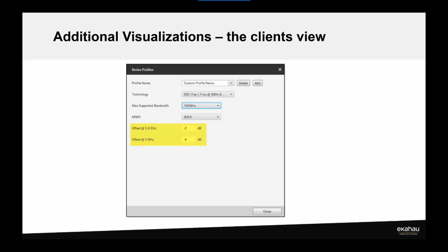And that offset is what makes doing this a lot trickier than it would sound initially. Because you may think, hey, I just want to see what it looks like from this tablet or this wearable device. And you can set up a lot of that just knowing generically what the device is capable of doing from the box it shipped in. But the offset is a lot more involved, and it'll take you a little time to figure out. So you want to find the exact value from the radio chipset manufacturer or a specification sheet, or measure it yourself, to make sure you're getting a value that is really meaningful and useful to this process. But if you don't put in an offset here, you're not really modeling much differently than what you find for the raw measured values.